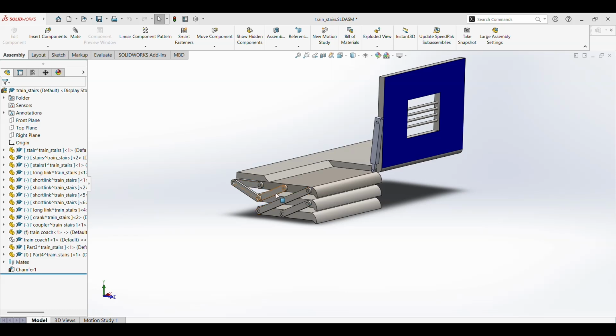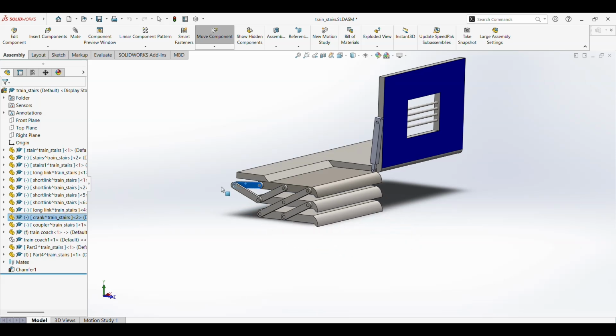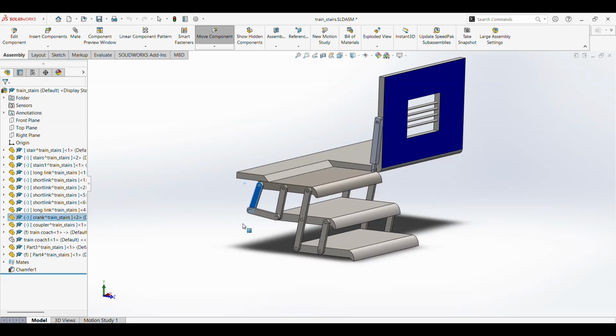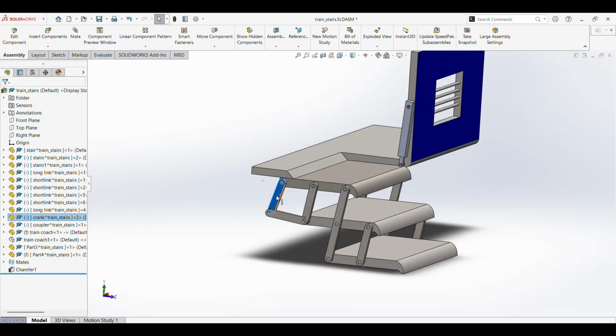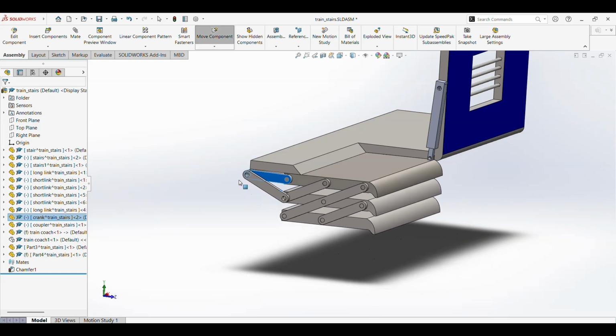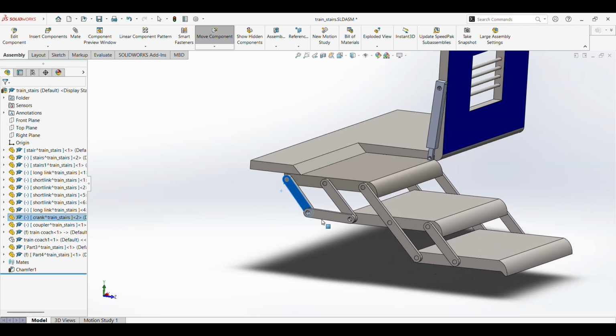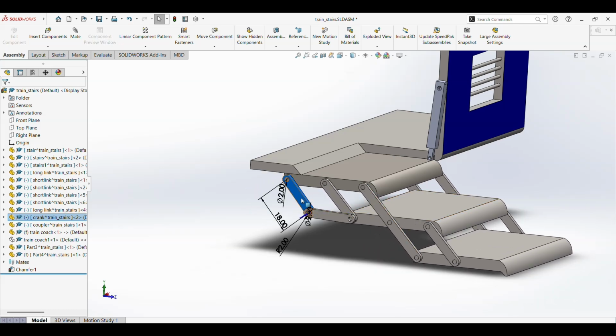This particular setup here is a 4R linkage, and this helps the ladder mechanism to move from the stored position to the extended position. This particular link that is marked with blue is connected with the actuator and it is basically rotating from 0 degrees up until 120 degrees when the ladder is extended. The dimensions are as follows. As you can see, these are the dimensions.